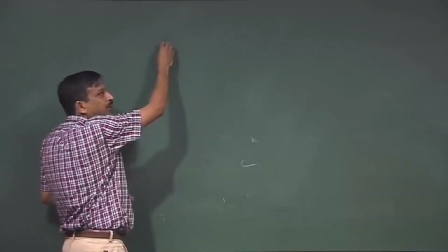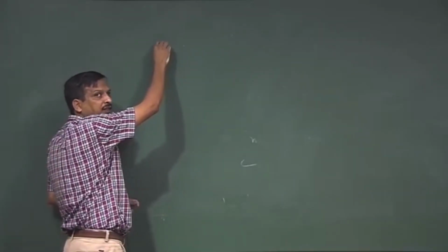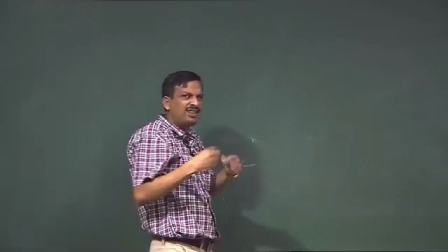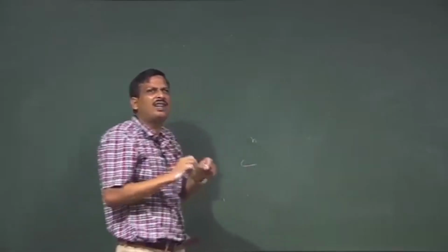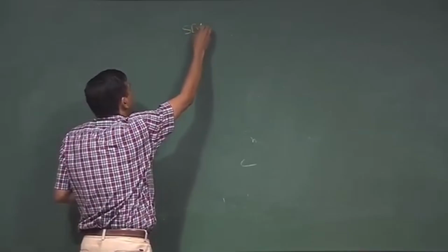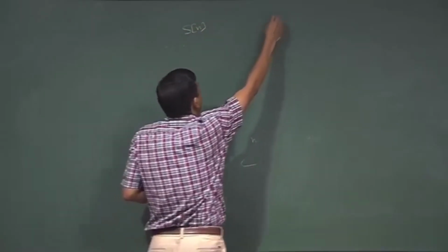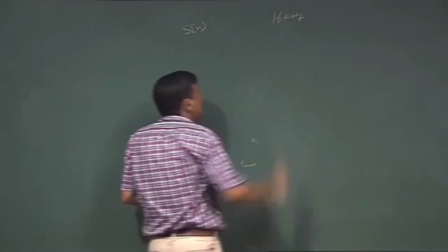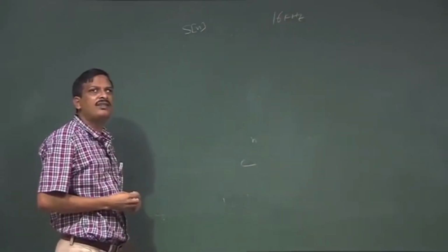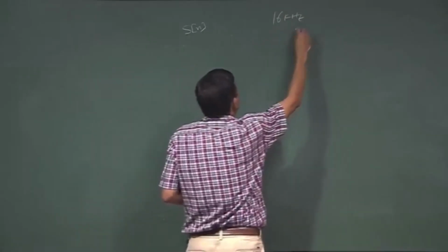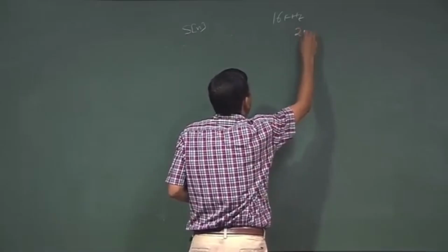Okay. So, what we said is that if the spectral coefficient is extracted from the mel spectrum, then we can get the MFCC. So, how do you do that? A little bit of detailed discussion on how to implement it. Suppose I have a speech signal, which is sampled at 16 kilohertz. And then I take a window length of, let us say, 20 millisecond.